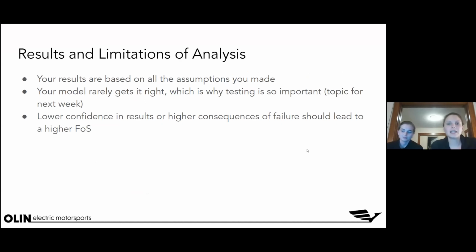So everything we have been talking about points to the fact that your results are based on the assumptions that you make in the beginning. So your model will rarely get it 100% correct, which is why testing is important, a topic for next week. But your model can definitely increase your confidence in your parts because it does better calculations than you can. Thank you, computers. If you are not confident in your model, or it has a really high consequence of failure, this should lead to a higher factor of safety.